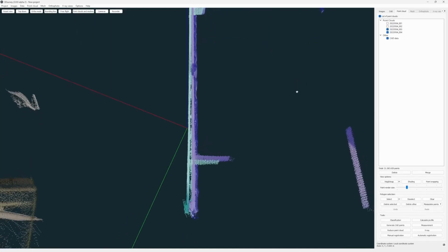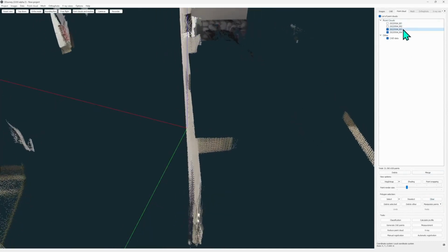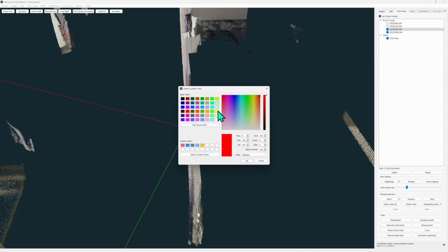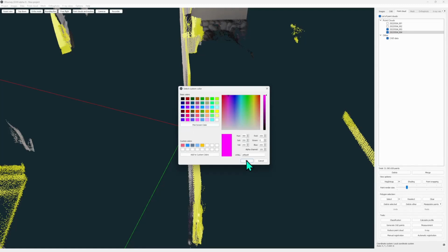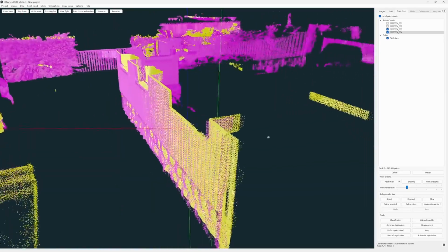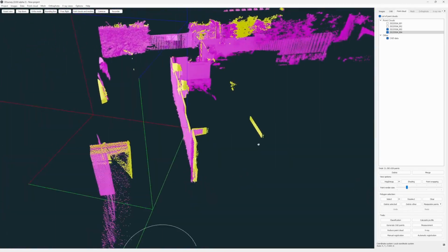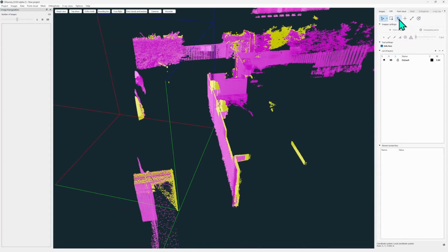So you have just the point clouds in question. And what you can do is you give them a specific color that is like temporary, just for visualization. So we'll make the first one yellow, and the second one will color magenta. This is very contrasty choice, and now you can clearly see the discrepancy between them, and we'll even measure it so we can compare our results.